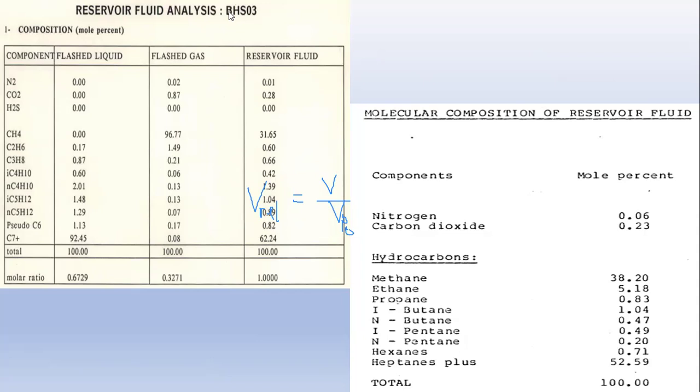Okay, no, my question is, how do we get these fluid samples? Is there an instrument that extracts the samples? When they finish drilling the well, for the bottom hole sample, they do a drill stem test where they test the pressure of the reservoir. And after completing that, they collect samples. There is a cylindrical column within the drill stem that collects the sample at the face of perforation, and they'll carefully lift it up to the surface and transport it to the lab. That's for the bottom hole sample. For the surface sample, drill the well, complete it, put in surface facilities, then they'll collect the sample at the separators.